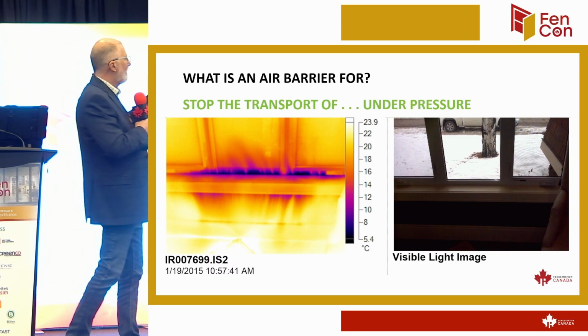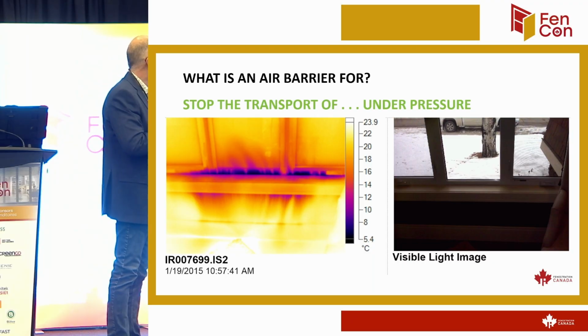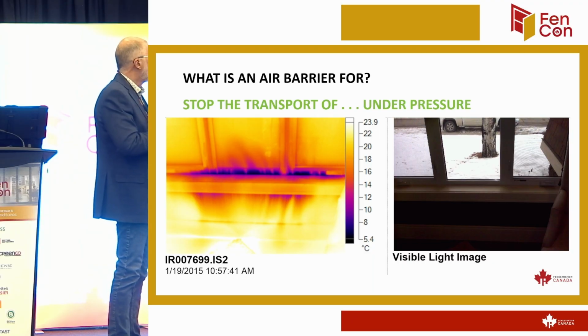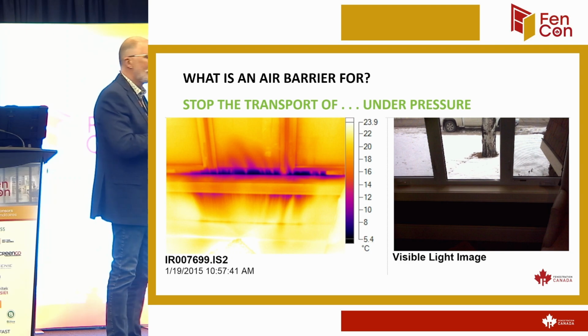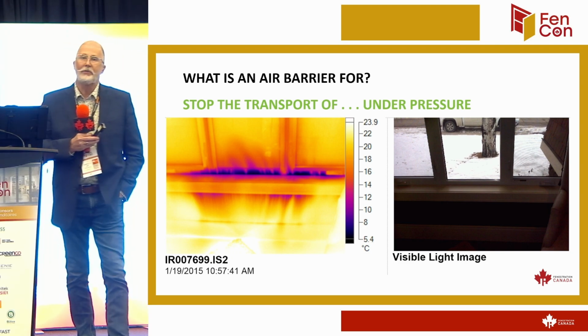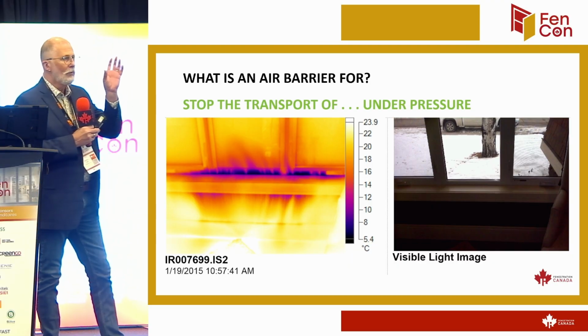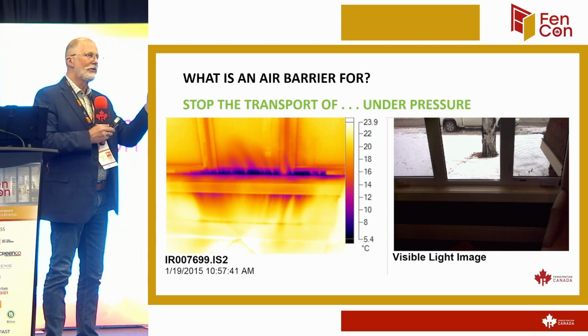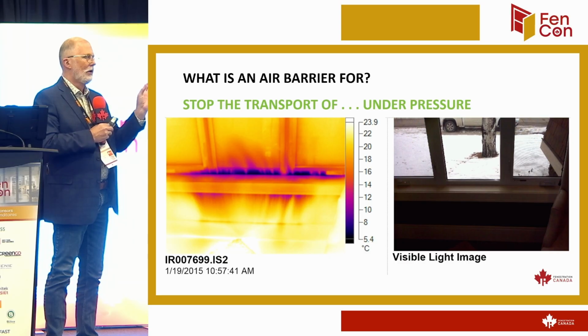And then we compare the air barrier. This is a very common situation we used to run into throughout my career in terms of people complaining about air leakage on the windows. Because in some of the western provinces, we buy the window with the jam extension already connected to it.